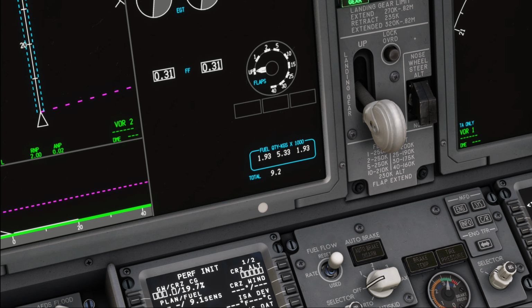So this alert is shown below the fuel quantity indications on the engine display, as well as the FMC CDU as a scratchpad message. A new non-normal checklist is associated with it, and fuel disagree is displayed when the totalizer fuel quantity and the FMC calculated fuel quantities disagree with one another.